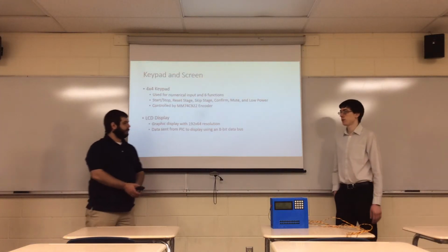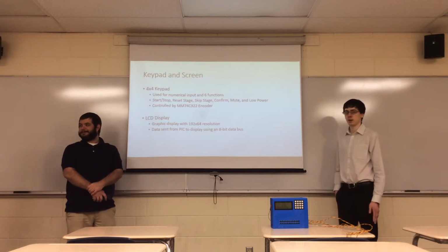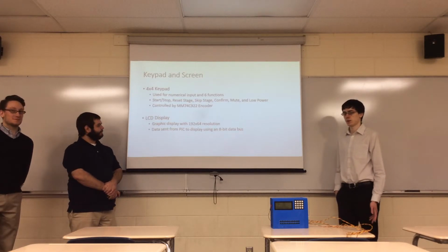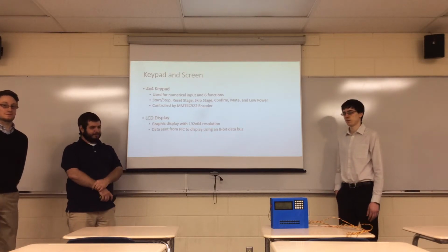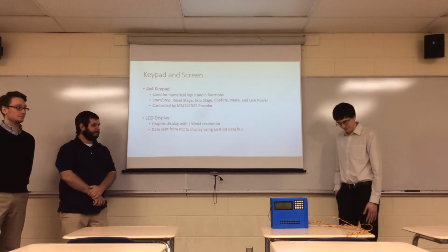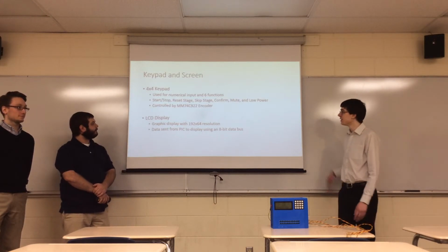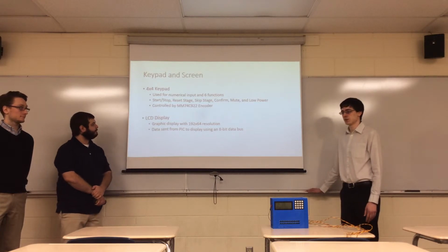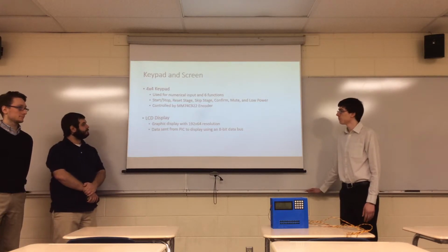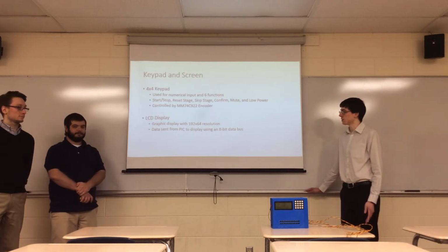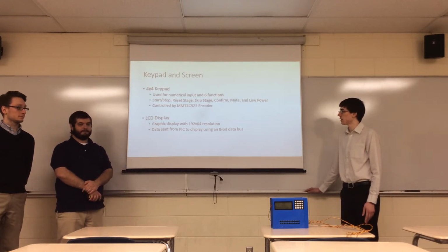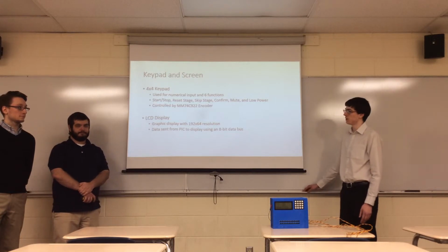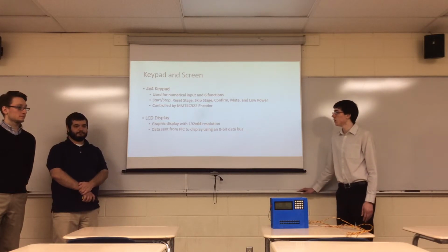So the keypad on our device, we use a 4x4 keypad with numerical values and 6 alphanumeric values. So we use 6 functions for each of those, A through F. The functions assigned to them are start and stop, reset, skip, confirm, mute, and toggle low power mode.